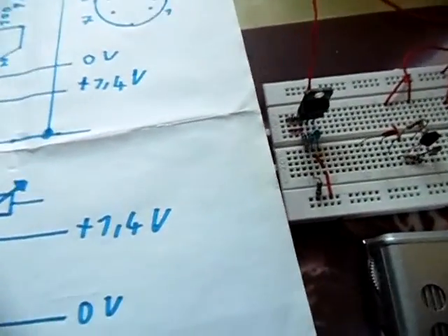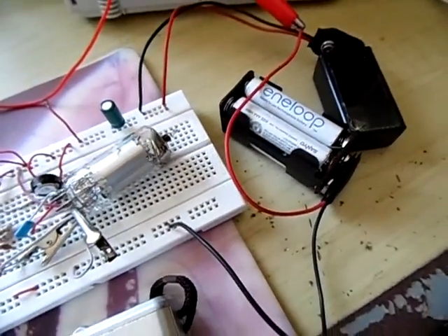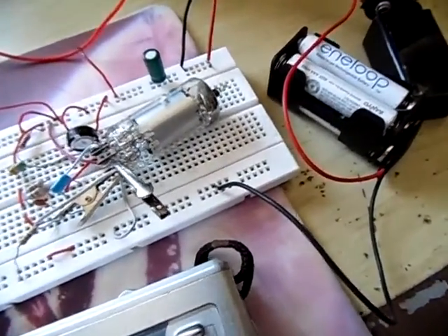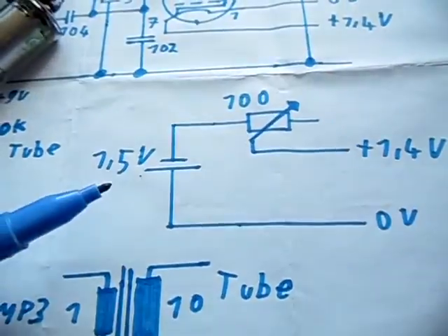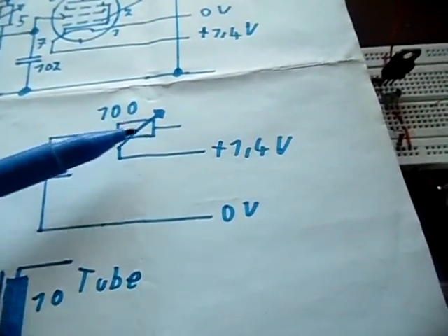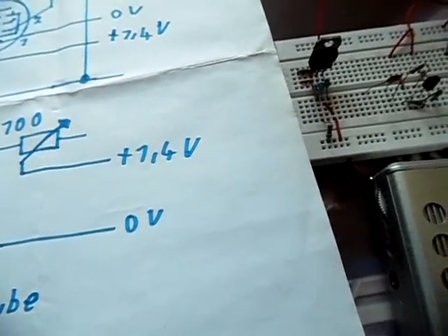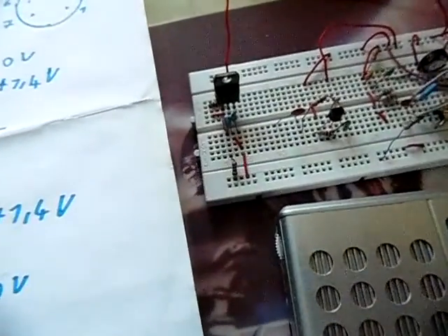And this is not good because an AA or AAA rechargeable battery has like 1.2, 1.25 volts, which is too little. And the new battery has 1.5 volts. So one thing that you can do is buy one of these big mono cell batteries, use a potentiometer in series with this battery and align it to 1.4 volts. The next thing I will show you practically.